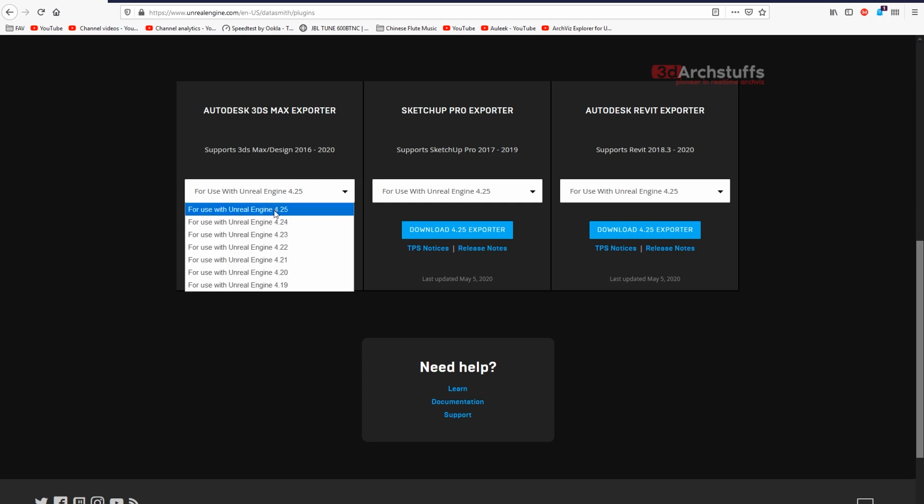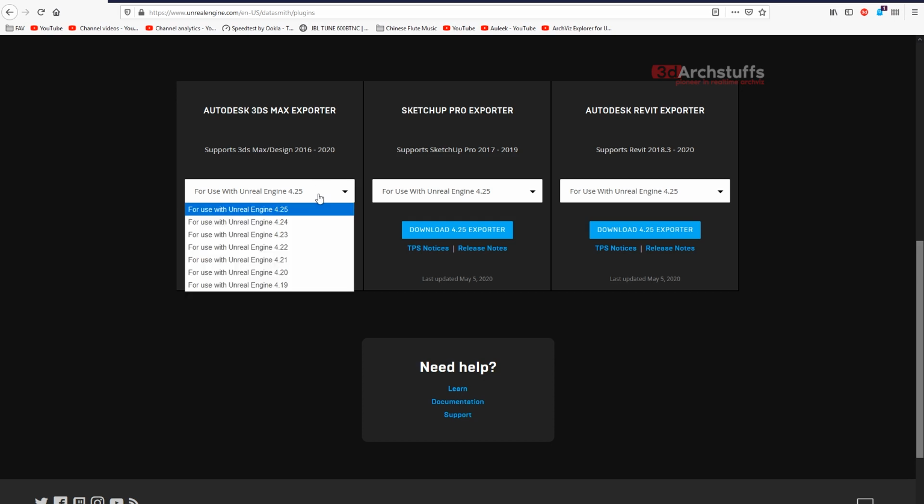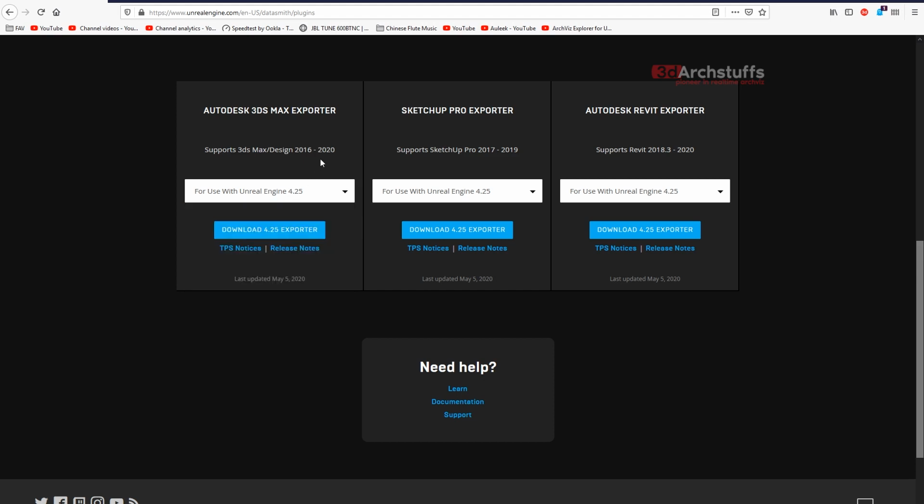You just have to pay attention to which 3ds Max version you are using for optimizing and exporting the scene, and which Unreal Engine version you are using for importing and working in the project. So install the exact DataSmith version related to the version of Unreal Engine you are going to use.